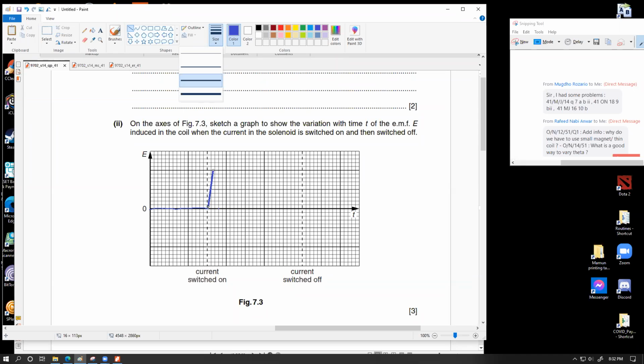Actually, these things are going to be smooth curves. You're going to have a sharp peak over here. You're definitely going to have a corner over here, but the bottoms can be rounded. They usually become rounded. I'm not getting into the reasons why they are supposed to be rounded. If you want to use a ruler, go ahead and use a ruler. No big deal, you will not be losing marks for it. So you show a spike over here, and then you maintain this 0 current up to the point the switch is opened, and then on the lower side you show that same thing for a duration of 3 divisions. So the spike is at 10 division bottom and 0 comes at 10 division top.